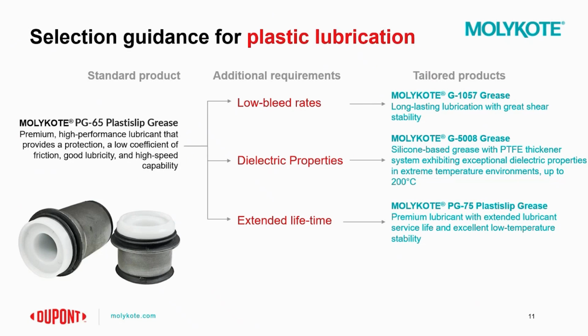If you're looking for plastic lubrication with dielectric properties, again, you could look at G5008, which is specifically a dielectric grease. It's a silicone-based grease with a PTFE thickener system, and it's ultimately that chemistry which lends it its exceptional dielectric properties, specifically in high temperatures.